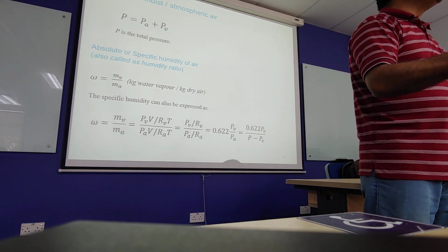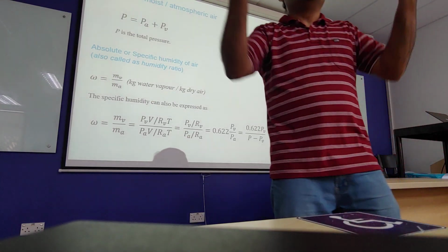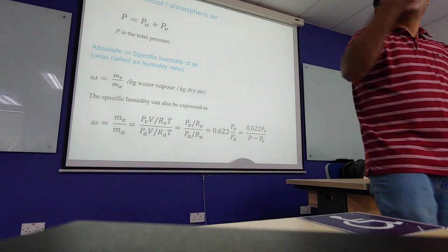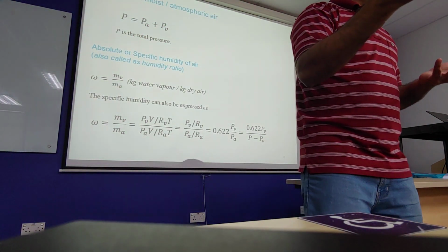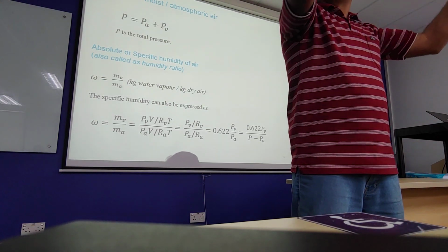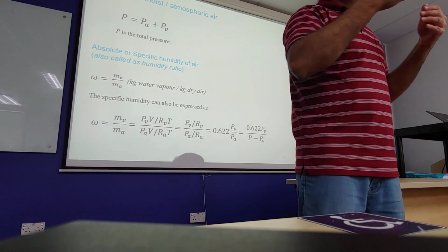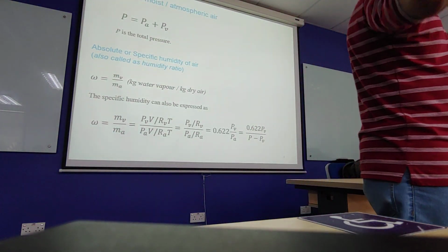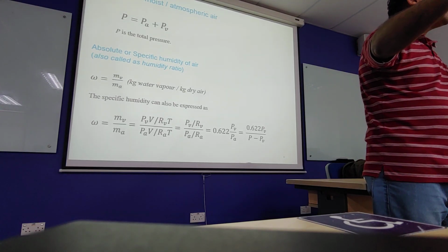When it's very hot, do you sprinkle water on your face to cool yourself down? Why does it cool you down? Evaporation, but what's the effect? When water evaporates, what does it do? It absorbs thermal energy from the surface and uses that to evaporate. That's the latent heat of vaporization, very high. And can it happen continuously? Can you continue to cool yourself down by spraying cold water on your body, or is there a limit to how much you can cool down?